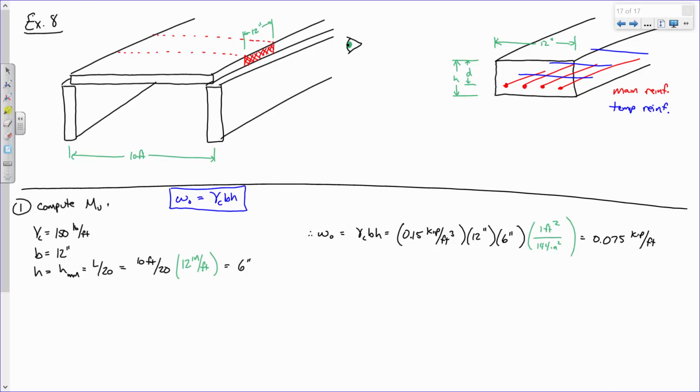If I have 200 pounds per square foot of live load on that floor system, how do I determine the load on that beam? By the length? It'd be the width. The tributary width, right? So what do you do? Okay, you would say, all right, let's take a look at this beam. The tributary width is about like that, right?